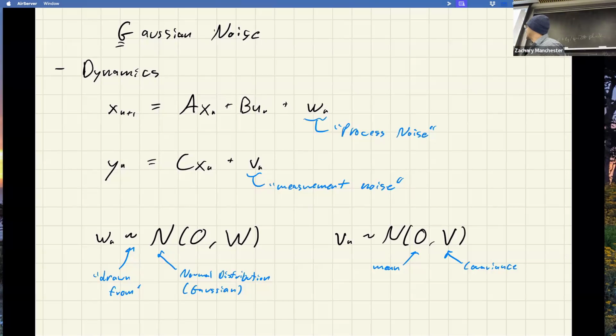So yeah, that's kind of getting at it. Because of linearity, if it does have a non-zero mean, I can basically put that in the dynamics and subtract it off. So the setup here encompasses having a non-zero mean as well. All I would do is, if I know the mean or the measurement model as an affine, then I would have affine dynamics, all the same. Doesn't matter. So you can always subtract the mean off in these things.